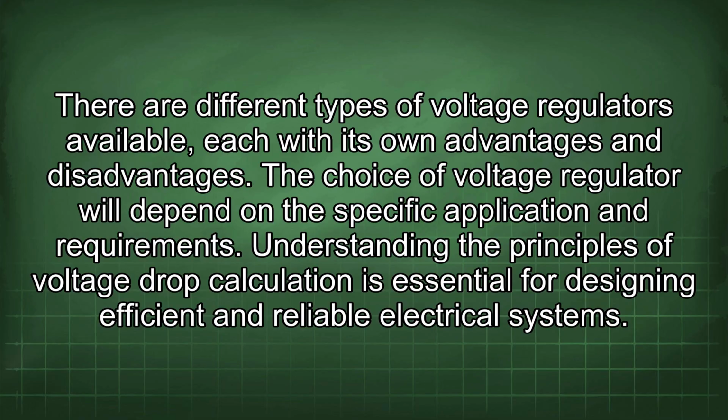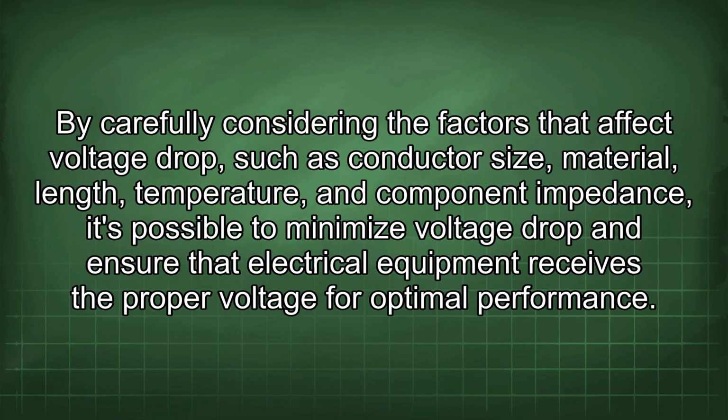Understanding the principles of voltage drop calculation is essential for designing efficient and reliable electrical systems. By carefully considering the factors that affect voltage drop, such as conductor size, material, length, temperature, and component impedance, it's possible to minimize voltage drop and ensure that electrical equipment receives the proper voltage for optimal performance.